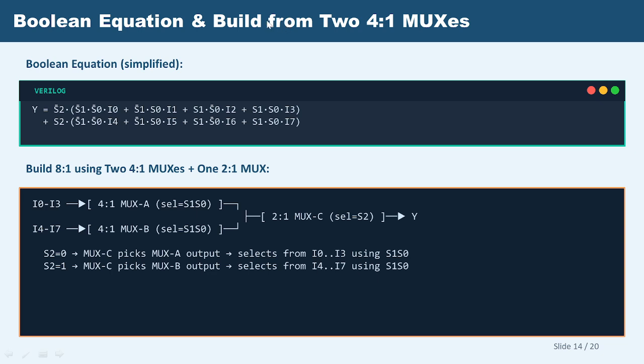In the first step there will be four 2-to-1 muxes. In the second step there will be two 2-to-1 muxes, and after that there will be nothing, right? So from 4 we get 2, and from those 2 we get the output. In total, how many multiplexers are there going to be? 4, 2, 1. So 7 2-to-1 multiplexers make an 8-to-1 mux.